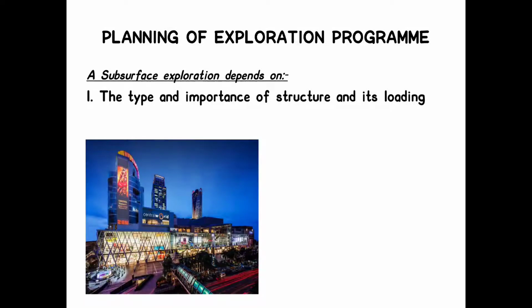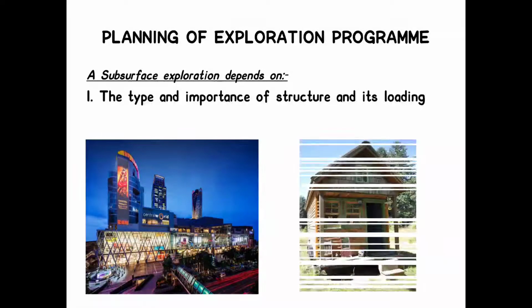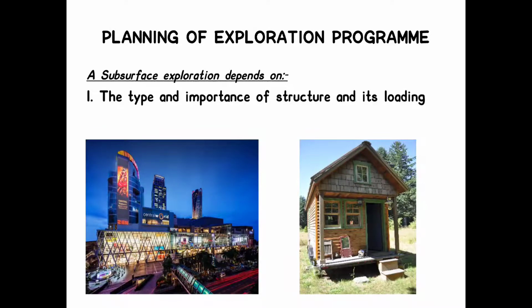Planning of exploration program. When you plan a subsurface exploration program, it depends on a number of factors. Firstly, it depends on the type and importance of a structure and its loading. Here on the left, we have a mall, and on the right, we have a small wooden house located on a fairly level and what seems to be a good ground. We know that the load that is coming from this mall, that is the public building, is much greater than the load that is coming from the small structure towards the soil,